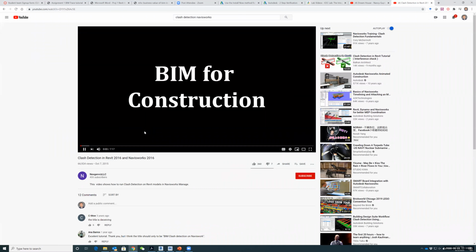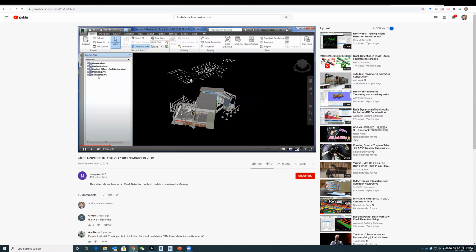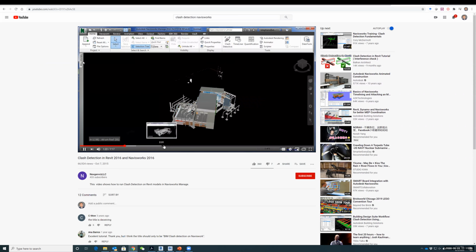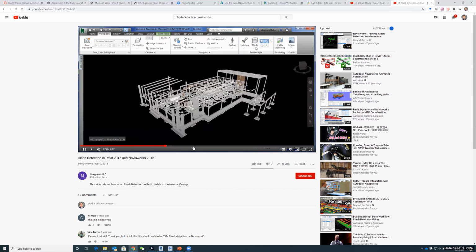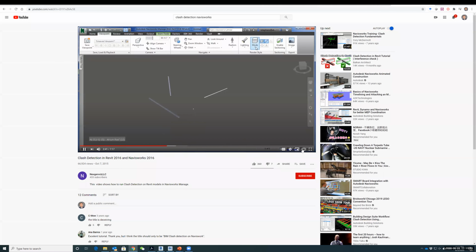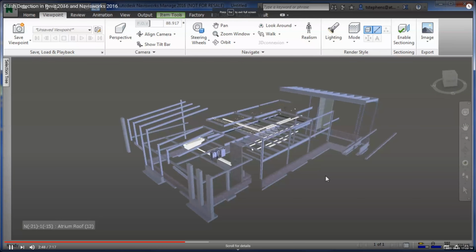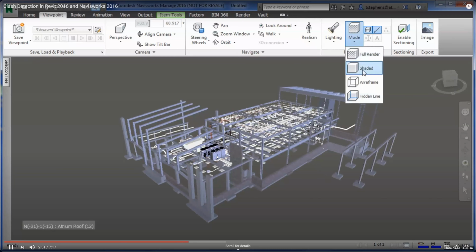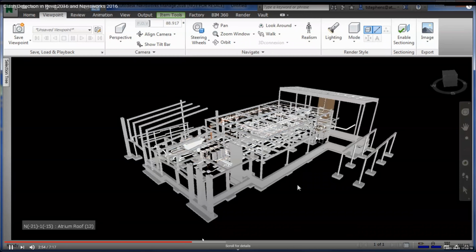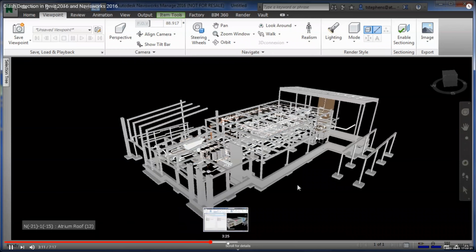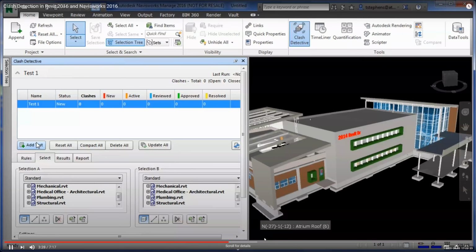Yeah, so I just found this is the program I'm going to use, Navisworks, and this is how it looks. So basically, you import a model here, and you run this clash detection. So let me see if we can go there directly. And it will tell you where the clashes are, like when this pipeline goes through the wall, or when the levels of a floor is not correct for a piece of machine. That's basically what you can find.